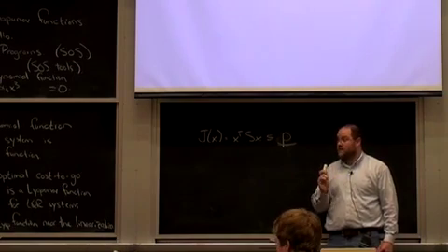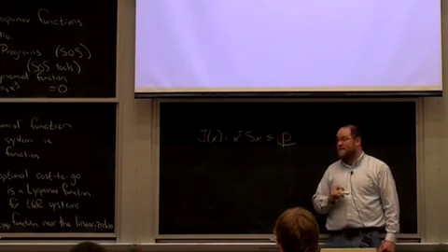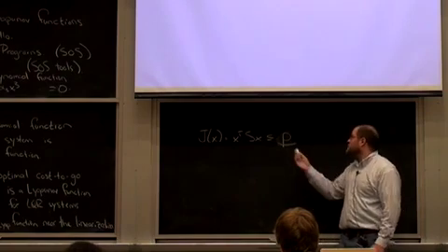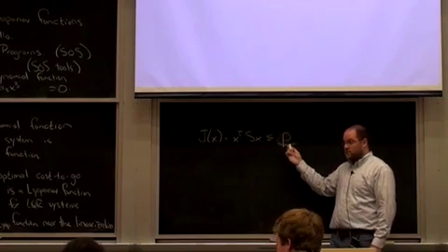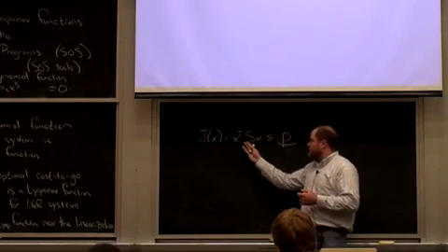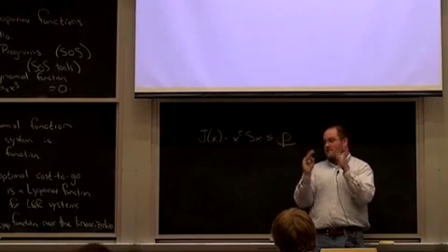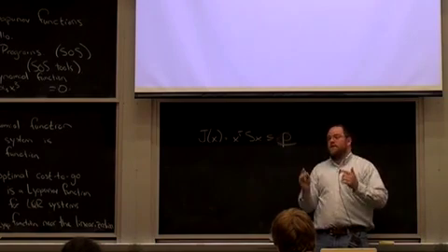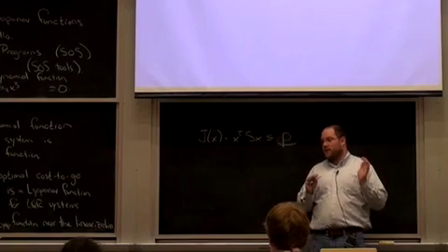Why would you use a particular cost to go rather than looking at what the variation is from the linearization? That is, we're going to determine this by looking at the variation based on the linearization, right? So I could do this in a lot of different ways. I could just look at boxes around my fixed point and try to design some geometry. The real basin of attraction is going to be some complicated thing, which depends on my LQR controller design and the way the nonlinearity affects it.